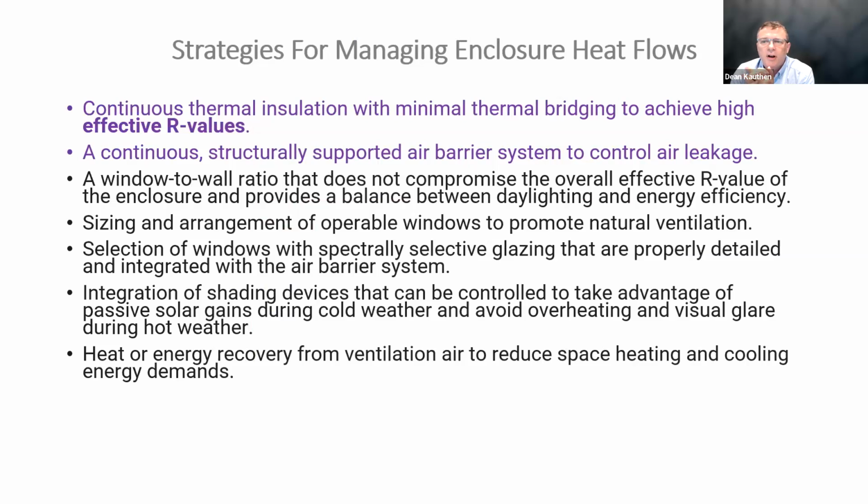So there are several components to managing enclosure heat flow, but today we can address the first two that we have shown here. We'll talk about continuous thermal insulation with minimal thermal bridging to achieve higher R values. And we'll talk about continuous structurally supported air barrier system to control air leakage.